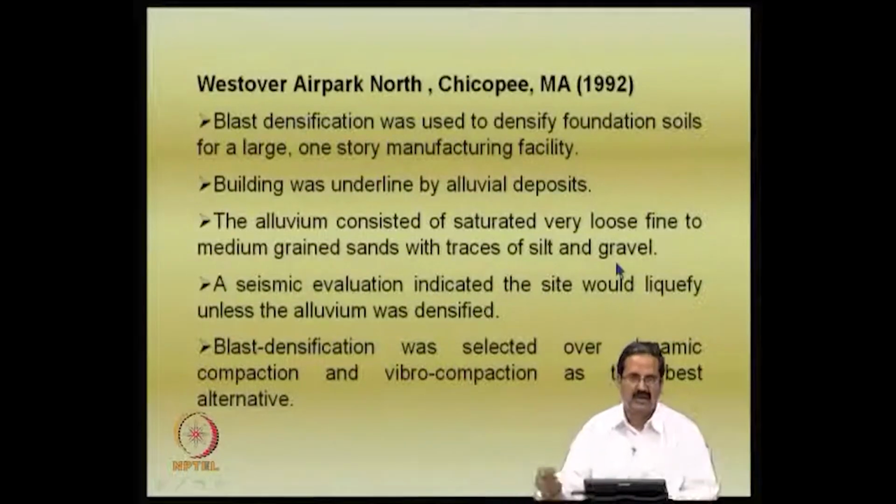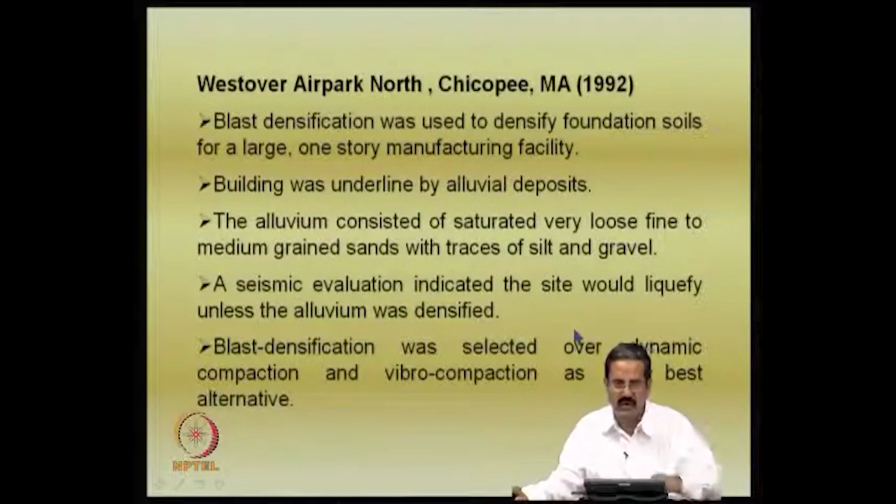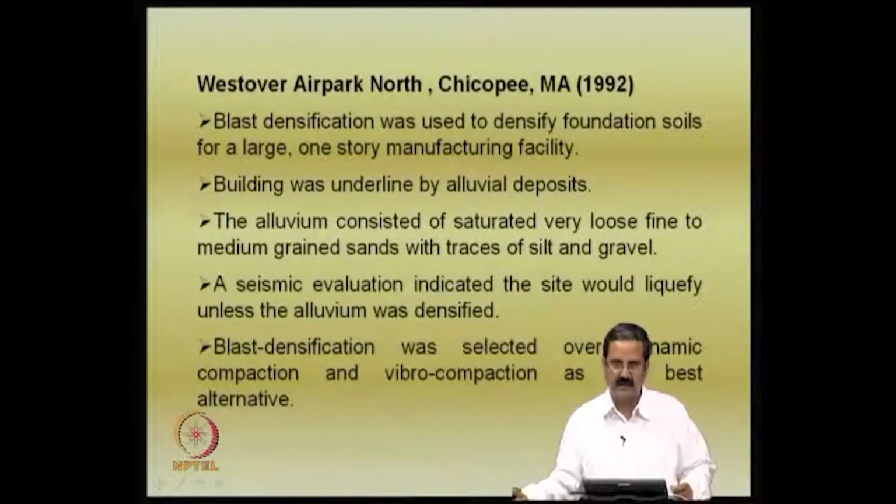So, the soil is very liquefiable. A seismic evaluation indicated the site would liquefy under the seismic event unless the alluvium was densified. If you do not densify the alluvium, you could have liquefaction, and that could really lead to damage to the manufacturing facility. That is the inference.